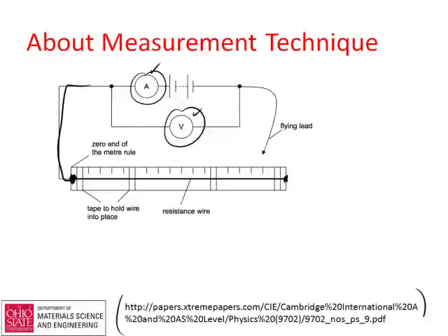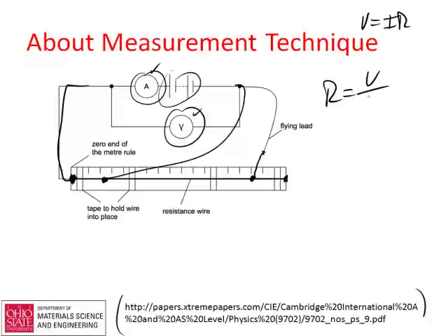Couple the lead to one side, measure from the voltmeter on the other side, and you'll find that as you go down here, you see a much higher voltage. Both voltage and amperage will change depending on how you do this. You'll see these readings change, and you can figure out what the resistance is. I always have to do this: V equals IR, so resistance is voltage over current. You can measure those two things and come up with that.